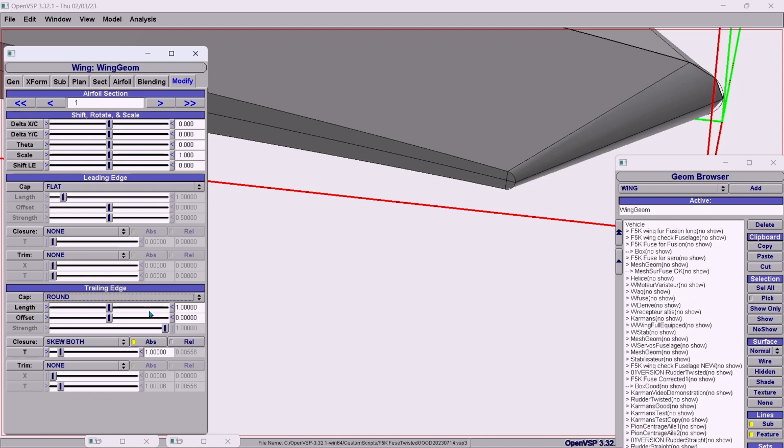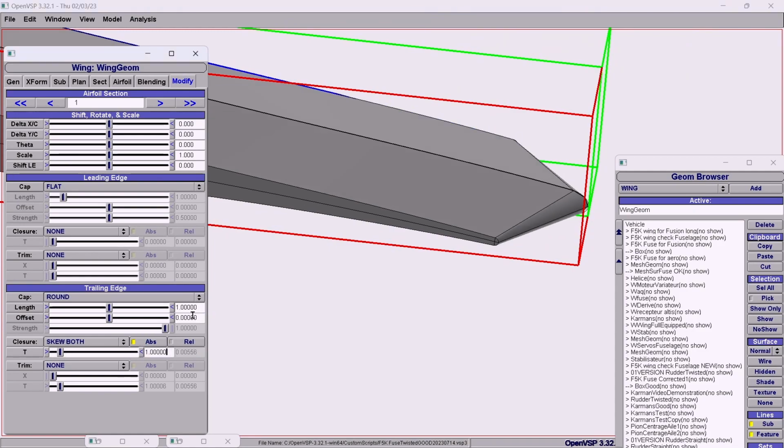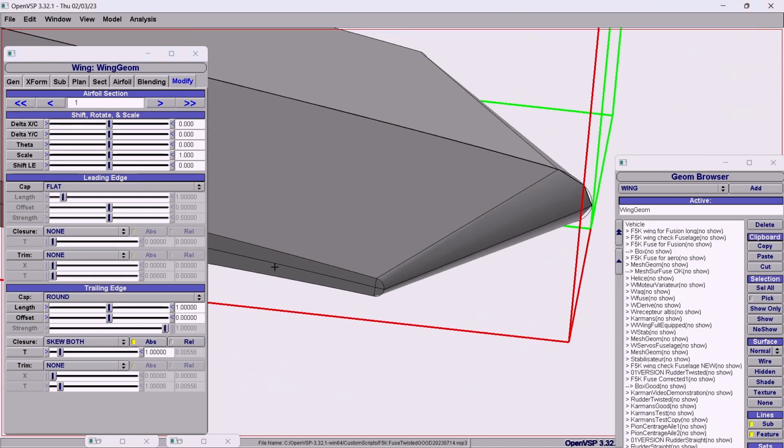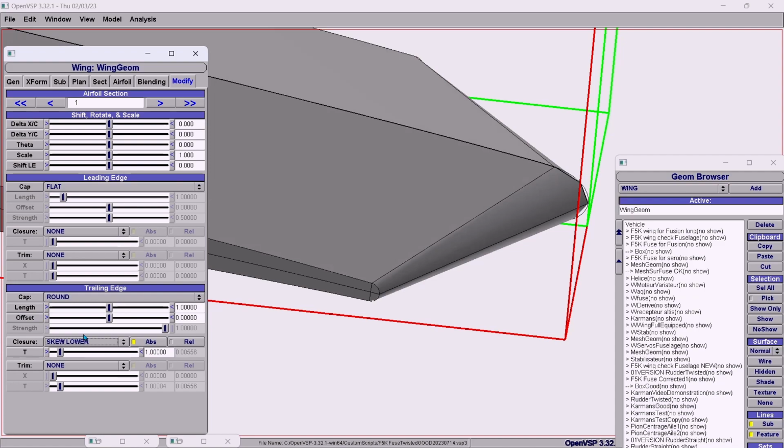I have the control I want. I can ask in relative, 1% relative, but in fact, I prefer to control in absolute and use 1 millimeters, which is not the same as 1%. I can move the line up or down, which will not be the same.